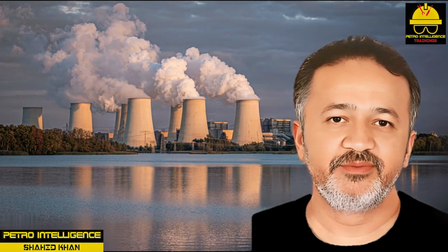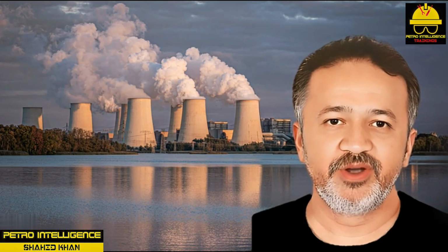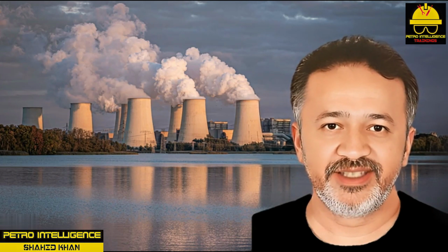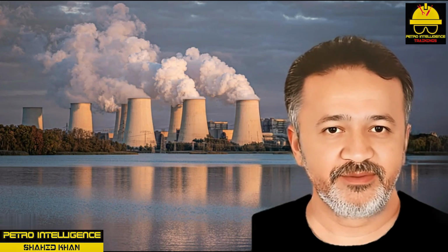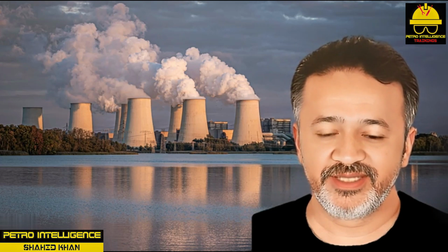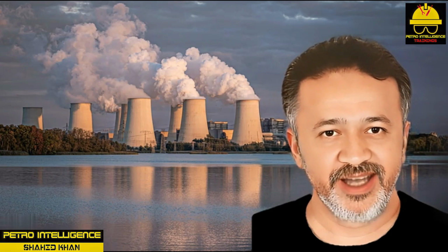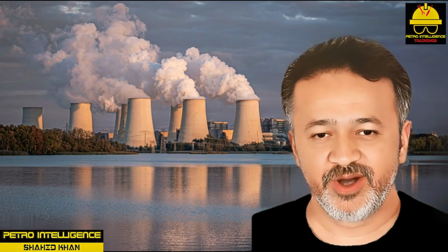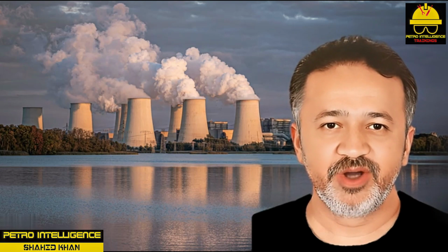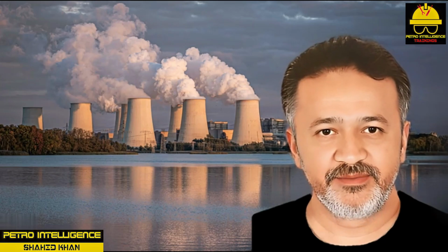Dissolved gases. Cooling tower water may have dissolved gases like oxygen, hydrogen sulfide, and carbon dioxide that chemically react with iron. These gases will enhance corrosion, destroy metal surfaces, damage valuable equipment, and deteriorate metal pipes, brackets, and bolts used to secure wood products together. High quantities of dissolved gases will make the catch basin water acidic.